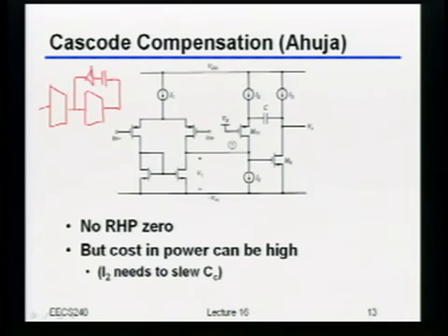Okay? Now, he built this as a common gate amplifier, because if you sort of pay attention to the signs of things, you want this feedback here, and I'll be careful. You know, if both of those have negative gain, you really want that feedback there to have positive gain. Right? If it doesn't have positive gain, then actually you'd be creating a positive feedback internally in this structure, which obviously you don't want. Okay? So if you want positive gain, and obviously you don't want to do that with multiple different stages, that's why he used this sort of common gate amplifier right here.